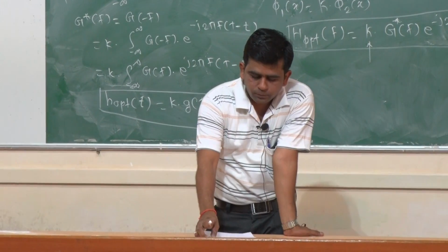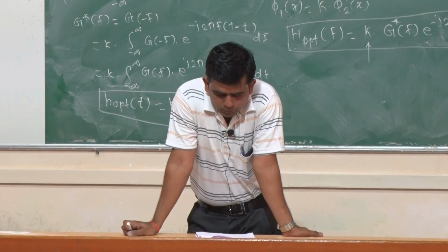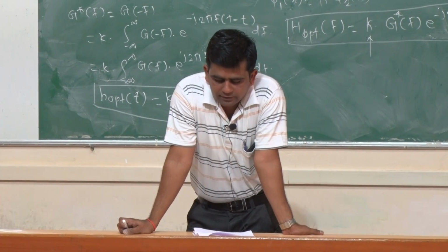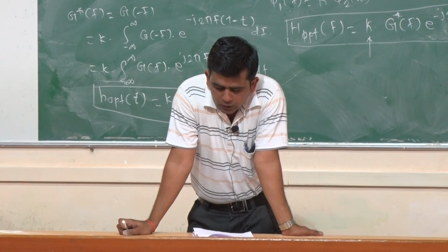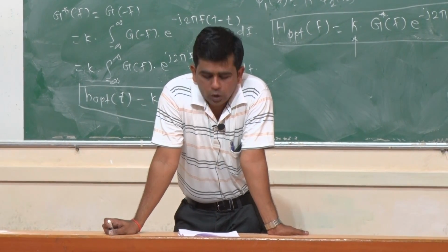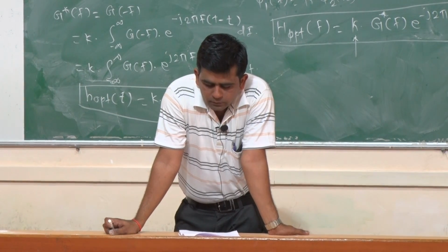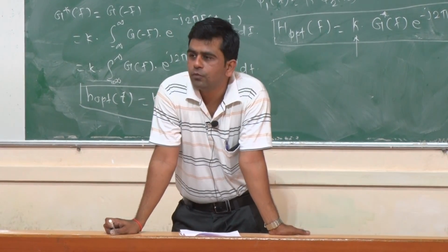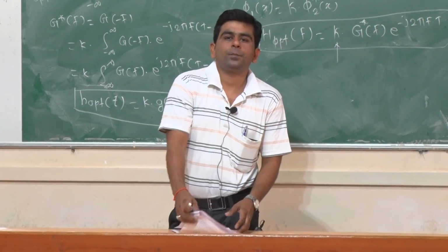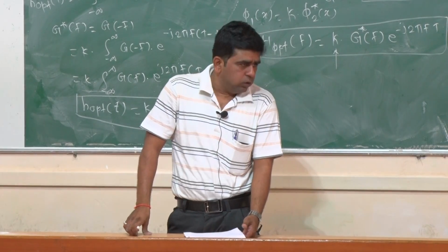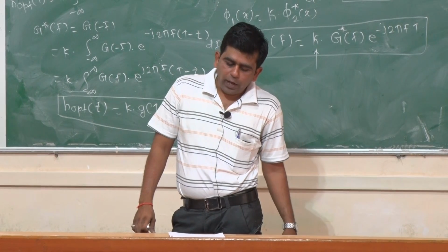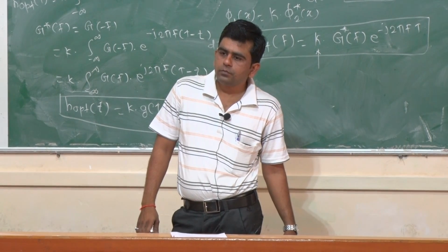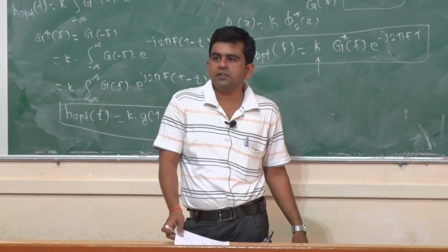Here the impulse response h of t optimum is a time reverse and delayed version of the input signal g of t, except for the scaling factor small k. Therefore, it is known as matched filter.